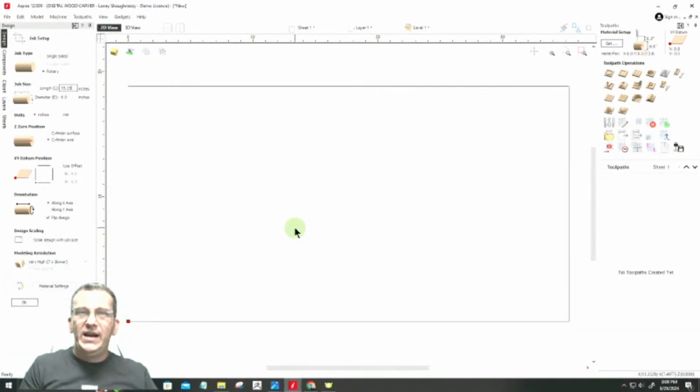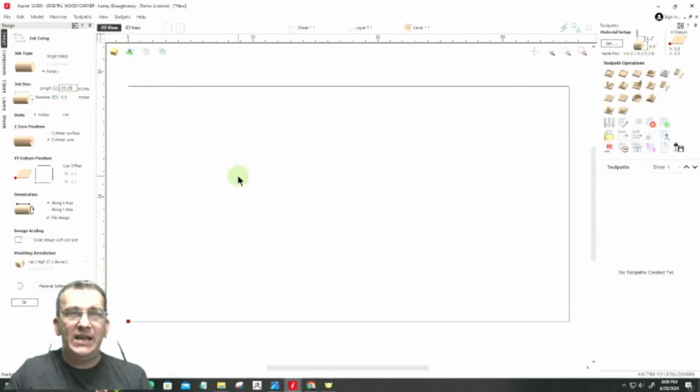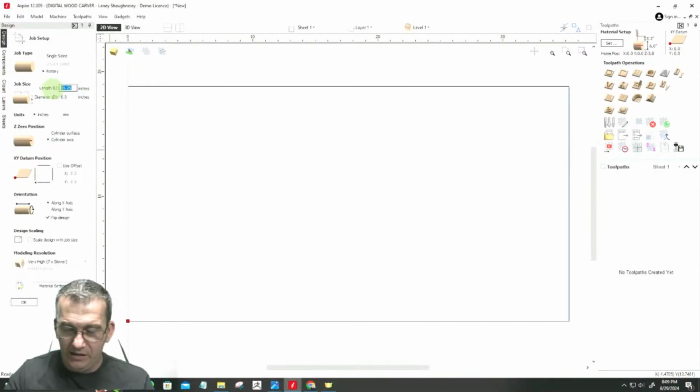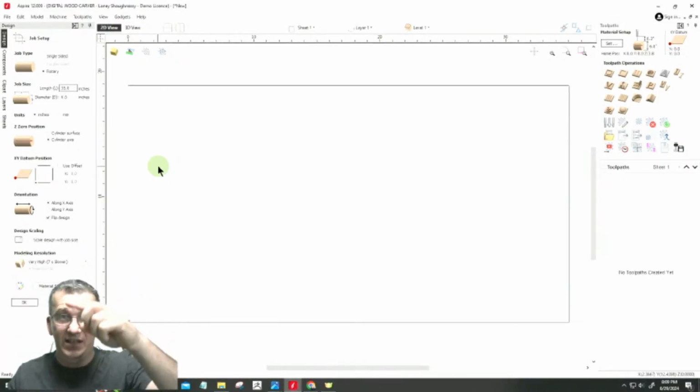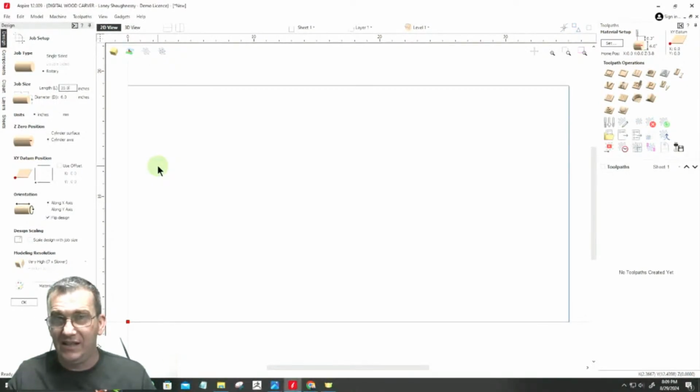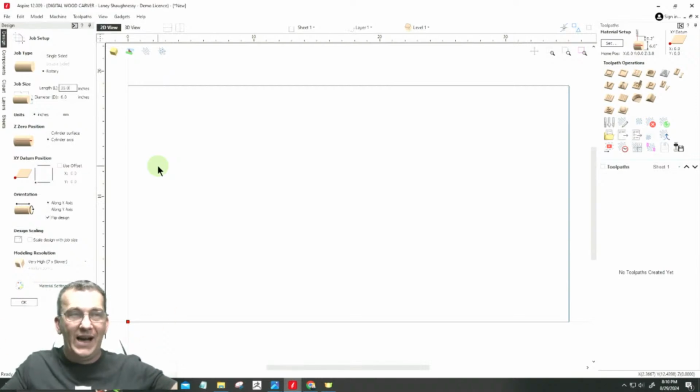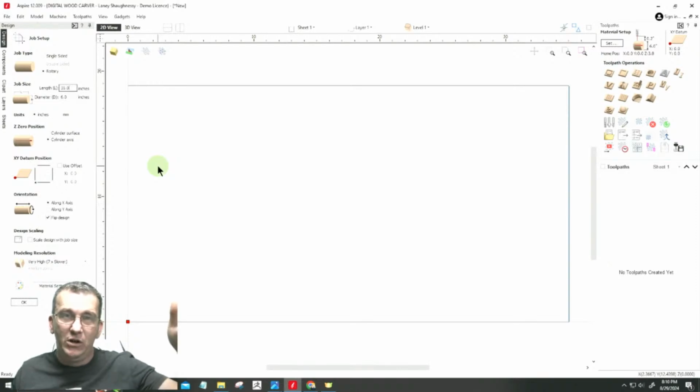I've taught it both ways. It really depends on what you're wanting to do. And let me see if I can make this a little bit clearer. If my part was 35 inches long in the software, but I allowed for a 1/2 inch of waste on each end at the table, and my blank was actually 36 inches, a 1/2 inch on the front leading end and a 1/2 inch on the tail end, that 36 inches. When I carve, I need to make a measurement a 1/2 inch over on my blank at the table, and I need to zero out my axis, whatever that length axis is.